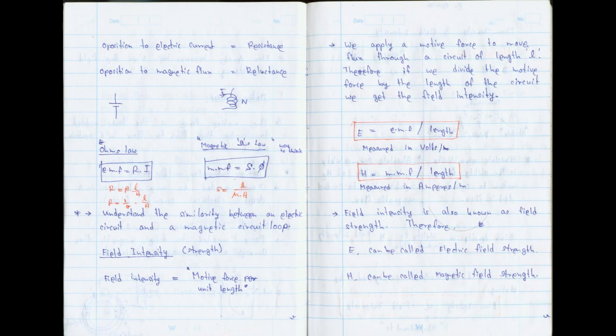If I want to measure the field strength of, say, the Rupavahini signal here, I get hold of the field strength meter, erect the antenna, typically 3 meters high, then adjust the dipole length to the Rupavahini antenna size, and then we will get the reading called capital E. And what is the capital E normally here? What is your idea? And the standard says it should be a little bit higher than 55 dB microvolt per meter. So that is the professional way of measuring. Then you know the signal strength level. You have now measured, you can compare with the others. It was invisible earlier, but now it is visible. Using meters you can always identify. That's the practical side of it.